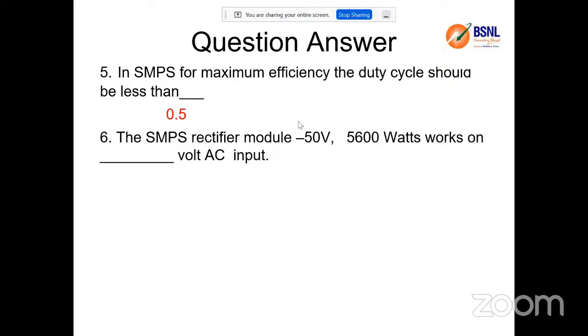The SMPS rectifier module, this much works on what voltage? It can have any range. That means the input voltage could normally be from three-phase voltages. Because of this, the 560 watt module will be on a three-phase voltage. Three-phase voltage can have variations of 320 to 480 volts also.